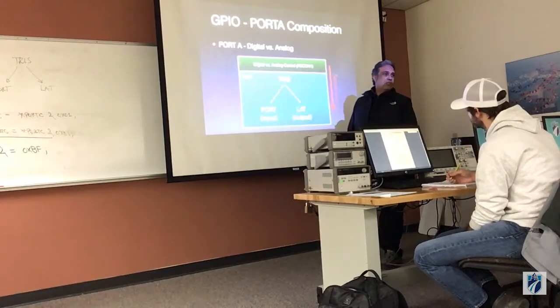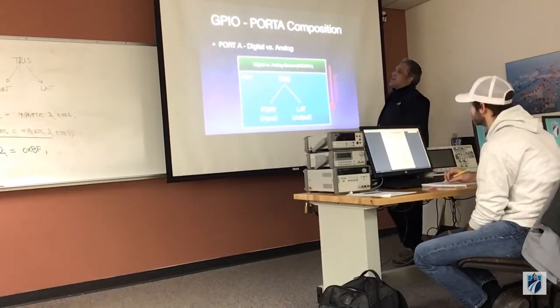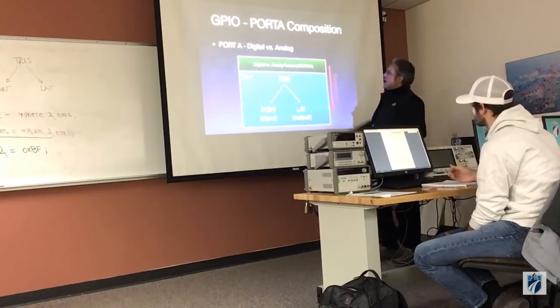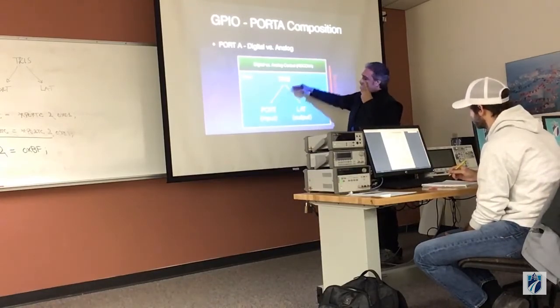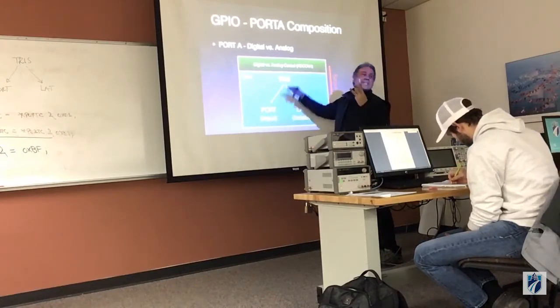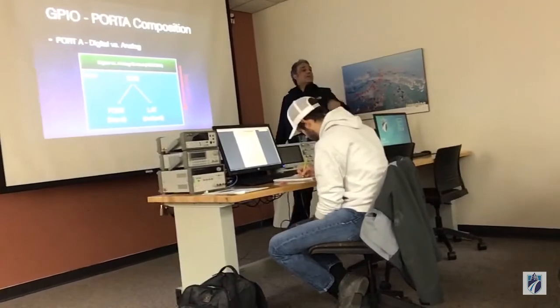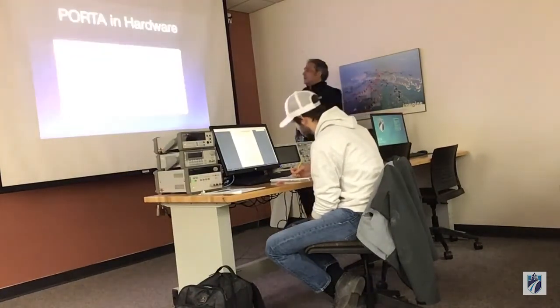So what's going to happen in software, the reason why I call these software considerations, is that you're going to have 3 instructions to manipulate one pin. You're going to have to control the AD con first, control the tris, then use the port. And it has to follow this sequence. Without that sequence, it will not work. At least it will not make any sense. Any questions?